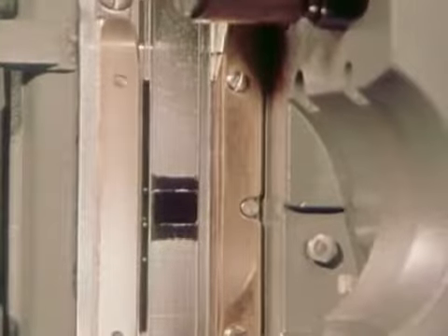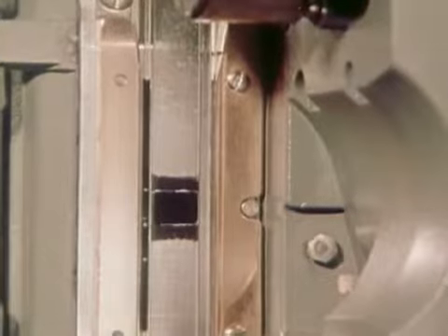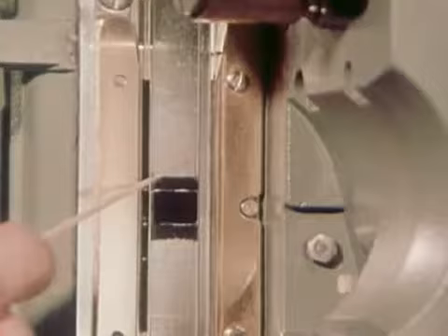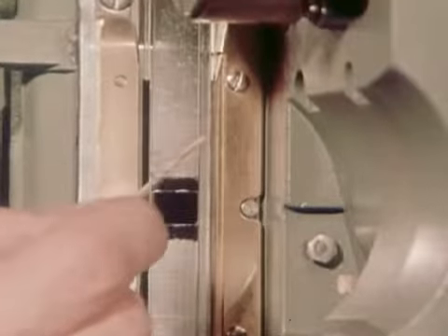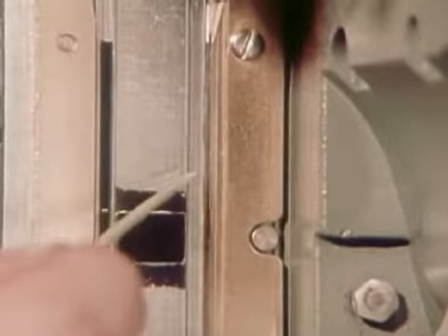Periodically, the film gate edges will have to be cleaned with a wooden toothpick, not a metal object, to remove caked emulsion. When the parts which contact the film are worn unevenly or are dented, scratching will result. Close inspection of the film gate will show that it is designed so that important parts of the film will not touch it at all. A path is hollowed for the picture area, and another path is hollowed for the sound track. Only the small remaining parts of the film touch the gate.